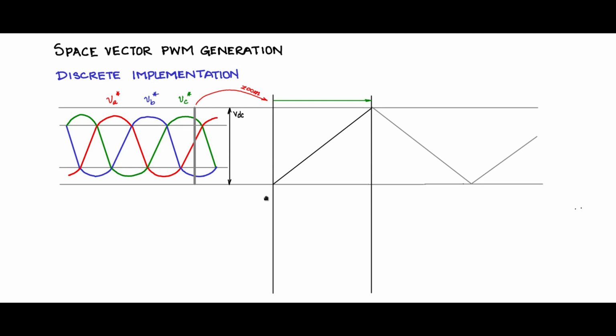So this time is TS, one switching frequency period or carrier frequency period. We will call that one TS. So you see, because of this linear conversion, the voltage can be converted to time because of this linear portion of your triangular waveform.